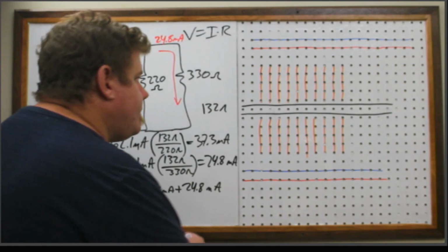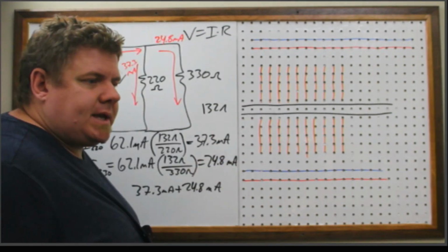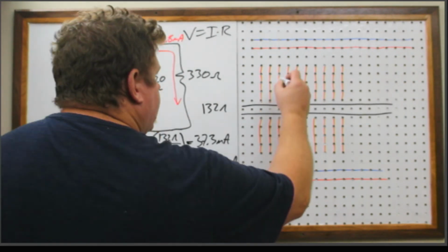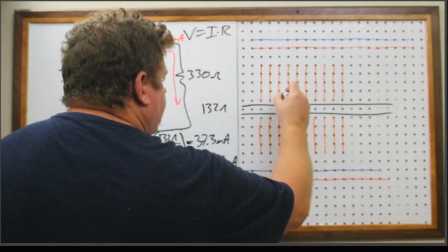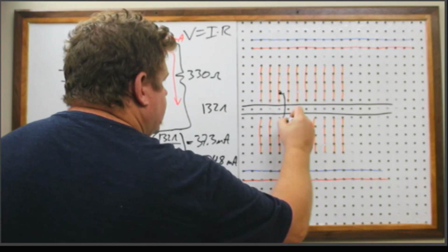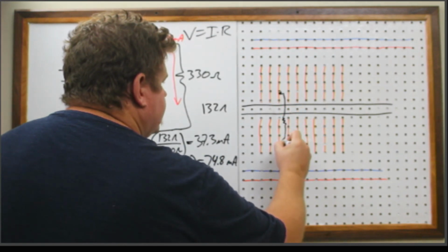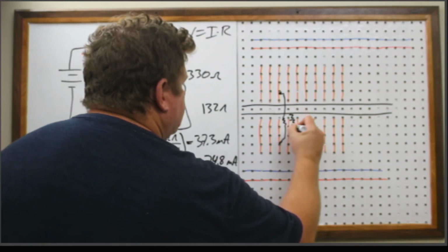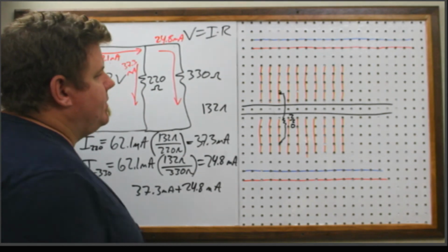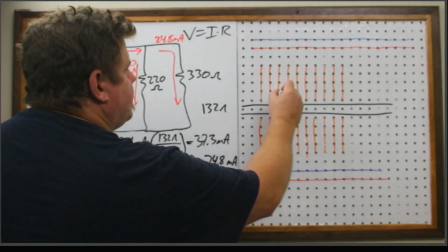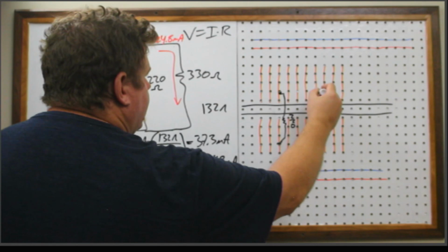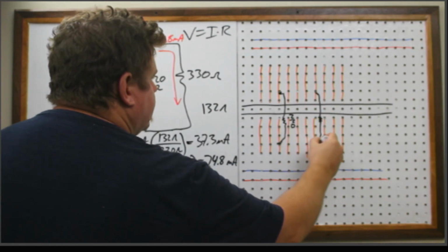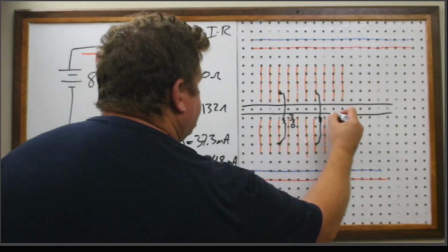So I'm going to bridge the gap here with my resistor. And yeah, I don't have any other colors. So I'm just going to connect from here over to here. Okay, and this is my 220. Okay, so just a spot over here and a spot over here. And then I'm just going to put somewhere over here in parallel just so I give myself enough room. This is the other resistor, and this is the 330.